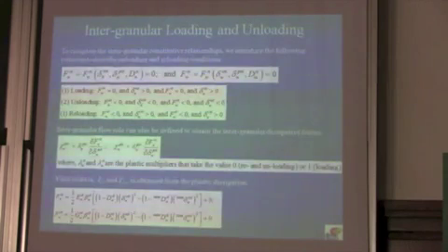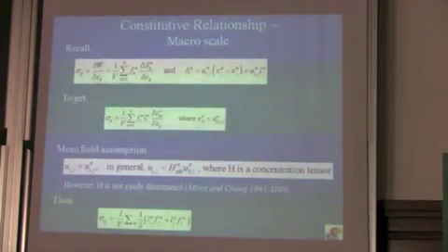All right. So far for the loading, of course, we would be incomplete without the loading and unloading part. So in the same way as we do in standard plasticity, we can introduce a yield function and define all these loading unloading criteria. In this case, we take the yield function to be just the plastic dissipation energy that we described previously. If we use this, which you saw earlier, as the yield criteria, then we find that the dissipative forces are the same as what we derived two slides ago. So we have a lot of confidence in this model.